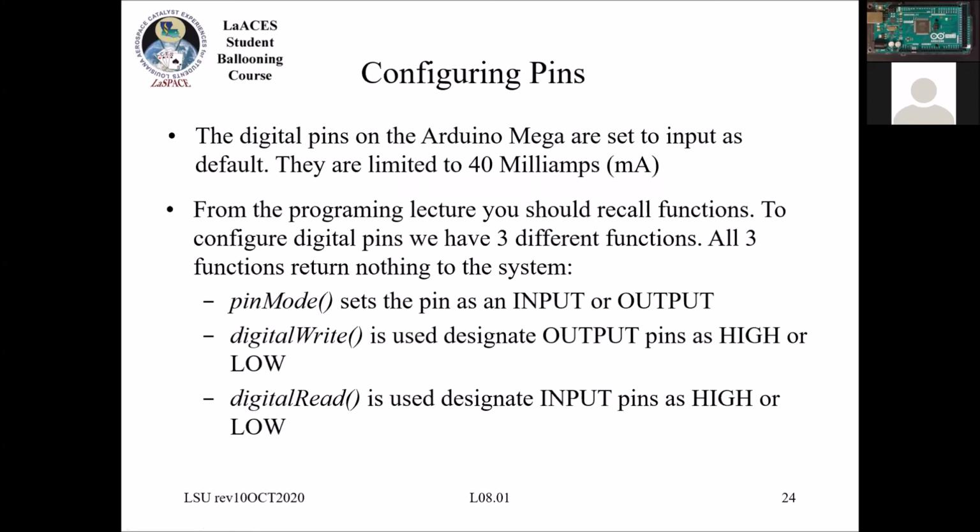So this is sort of the default configuration of the pins. They are normally set as inputs. If you want to use them as an output, you need to do a declaration. A key thing is the specification on the maximum current for these pins, which is 50 milliamps.